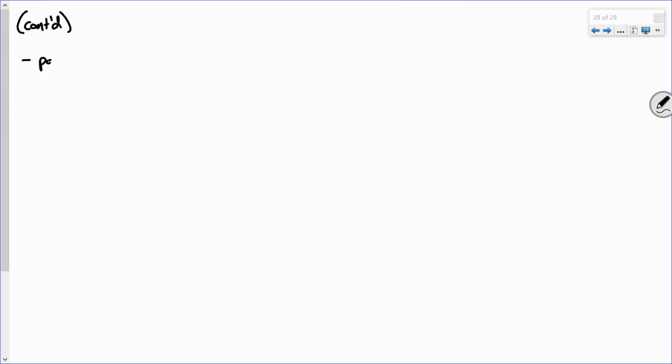All right. So part B. Now, we're given two things. Let's handle each of these one at a time. The first one says, what if tau allowable is 6,000 psi? Which should be a pretty reasonable thing to ask. If I got this shaft, and I know it's made out of steel, a particular grade of steel, this is the maximum amount of shear stress I'm going to allow it to carry. Maybe I should determine the maximum amount of torque I can put on it to generate that.